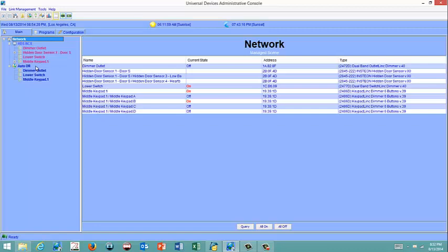There are 4 buttons on the bottom, and what I'm doing is pushing and holding on them right now. It's going to bring up another installer settings menu. As I click through that, I can go all the way down to where it says Zigbee Install. I am going to select that, and then I'm going to say yes, I want to add the thermostat. And this will go and add the Zigbee thermostat into the system. Now, while it's doing that and compiling that information, I'm going to go through a couple other things here.